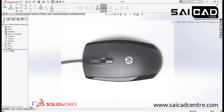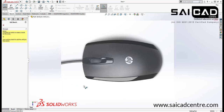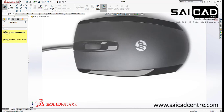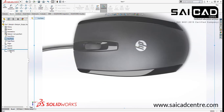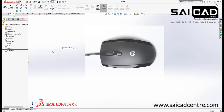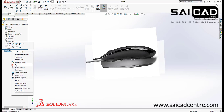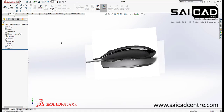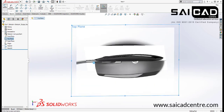So now go to the sketch, and you can use the tool from here. This is a simple arc shape, so I can just directly use the arc. So use the top view for your sketch. You can see we have a sketch 4 here also. So I'm just going to delete that one, and I'm just going to create a sketch at the top.